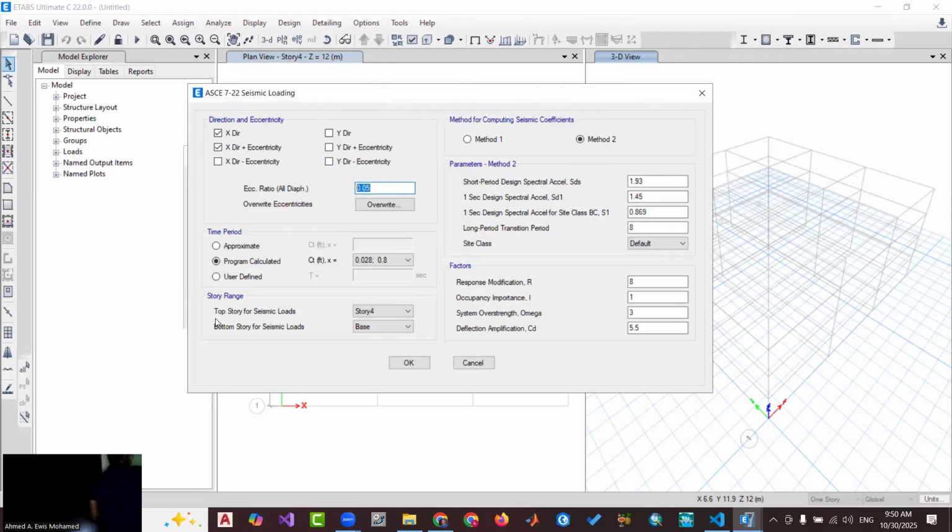So first, if they are not in the same place, for example, this center of mass and this center of rigidity, the force of earthquake applies here horizontally in the center of mass. This is a plane. Okay, and for the center of rigidity, this is the resistance, so it will be here. When you have two forces not acting at the same point, you should have what?